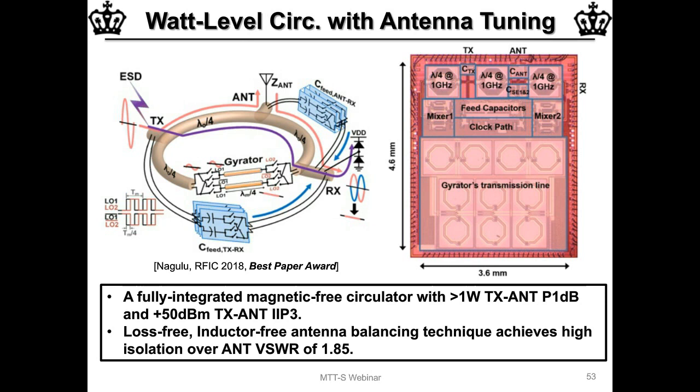Okay, great. Let's see. What about isolation for the on-chip circulators? Can you comment on any challenges associated with that? Right. So again, isolation. I think maybe this question comes from the fact that when you're on chip, there might be other leakage paths between the transmitter and the receiver that might limit the isolation.